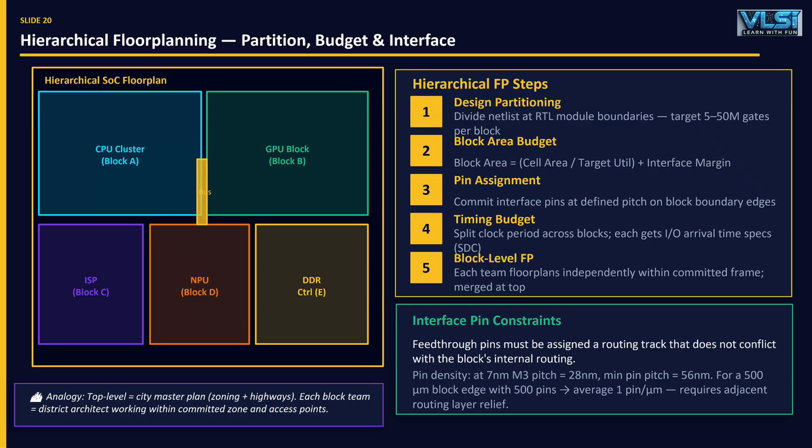Now here's the challenge. Coordination. If one block grows in size, everything shifts. If one block misses timing, entire chip fails. So interface pins must align. Timing budgets must be distributed properly. Hierarchical floor planning allows scalability, but requires careful planning because everything must fit together perfectly.